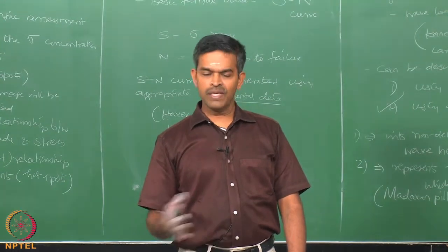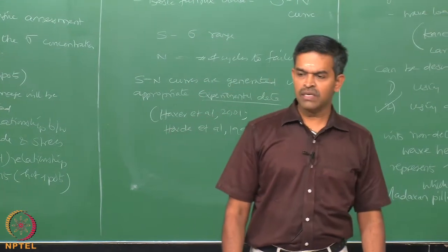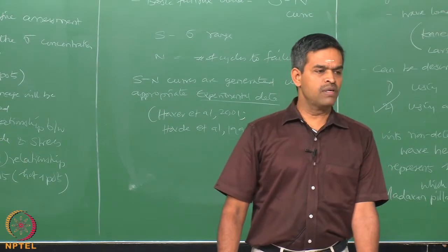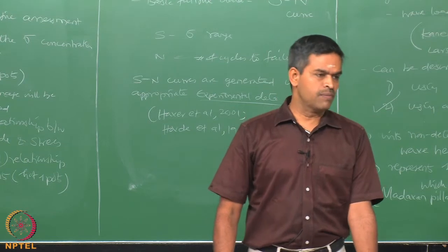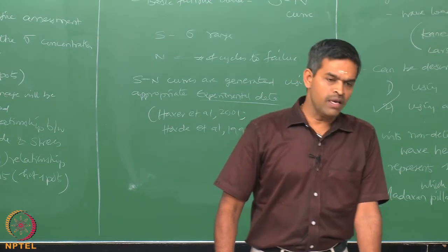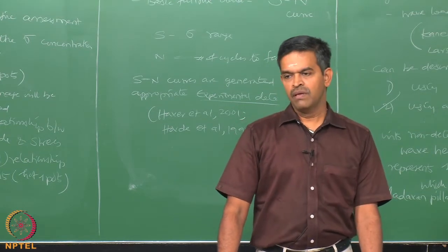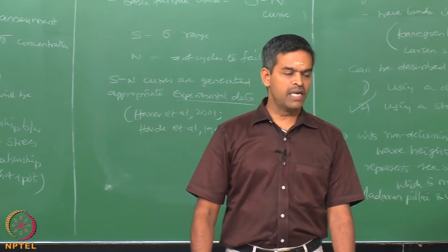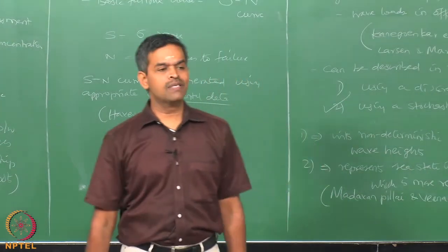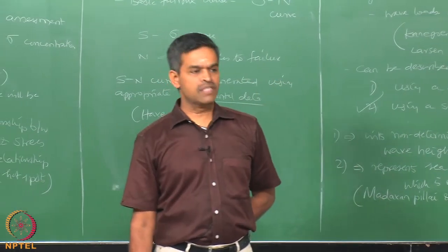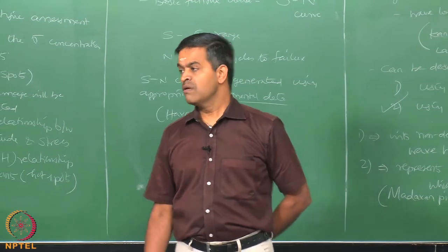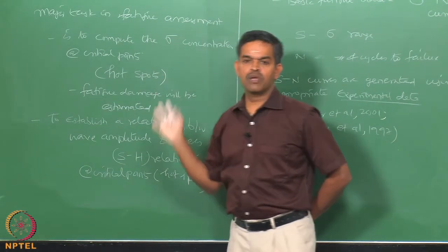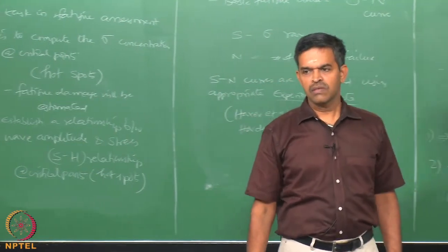Then we will take up a very specific example of estimating the stress concentration factor for tubular joints of different structural forms of geometric forms, which has been done experimentally, and then we will compare them with the empirical relationships given by international codes for our better understanding. Therefore, one can then explicitly understand the limitations of estimating the stress concentration factor, which is one of the vital requirement of fatigue assessment in a given tubular joints of offshore structures. Thank you very much.